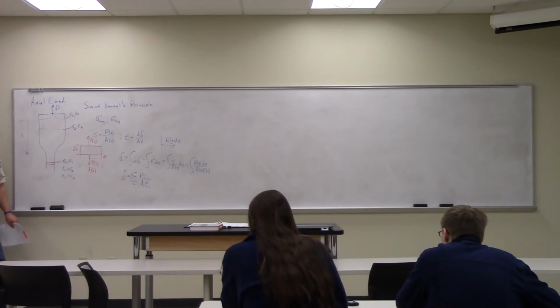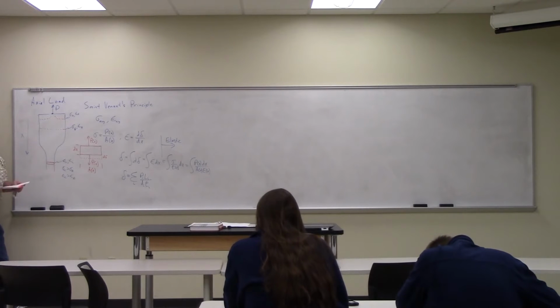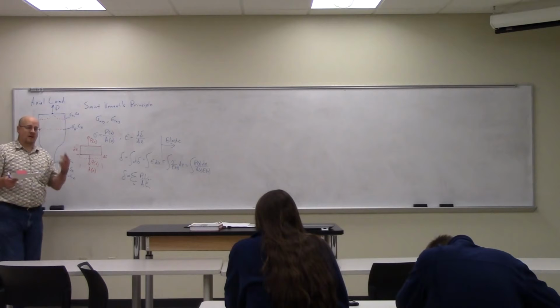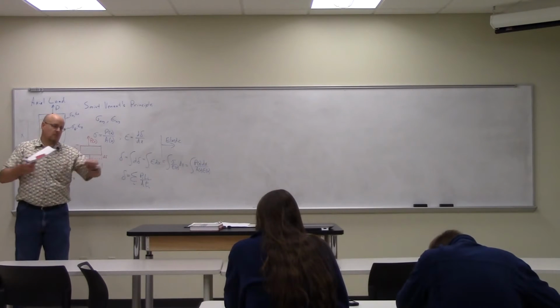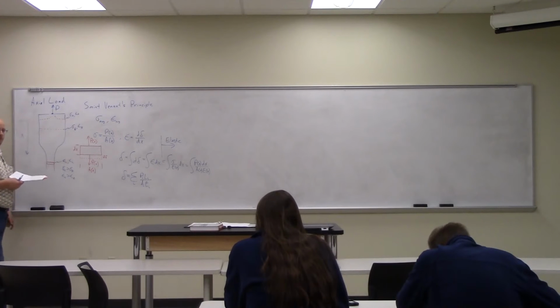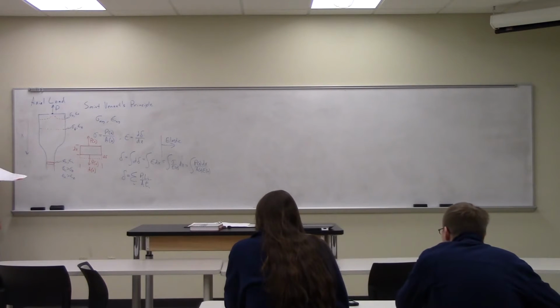So, does the E actually change very much? I thought that was a property. E would change if I had two different materials. So if I have a brass bolt mated to a steel bolt, right, so that's what's going to change. But if it's a uniform material, then E is not going to change. Okay.